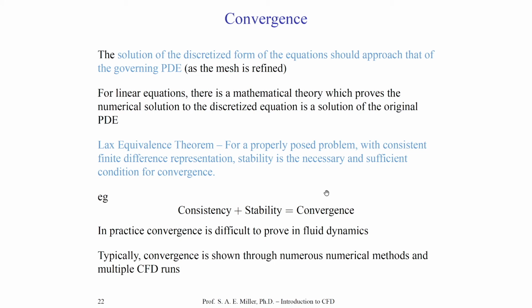It could be that you have a poor computational grid, which ruins consistency. It could be that you have a boundary condition with a particular flow that causes the solver to be unstable. It could be that you just chose a CFL number which is too large. Perhaps you've chosen a numerical scheme which is not stable, even if it's implicit, for a particular set of boundary conditions and initial condition. These are all possibilities, and it's going to be very frustrating. But this is part of what CFD is. It's setting up cases and trying them out to see if you can achieve convergence.